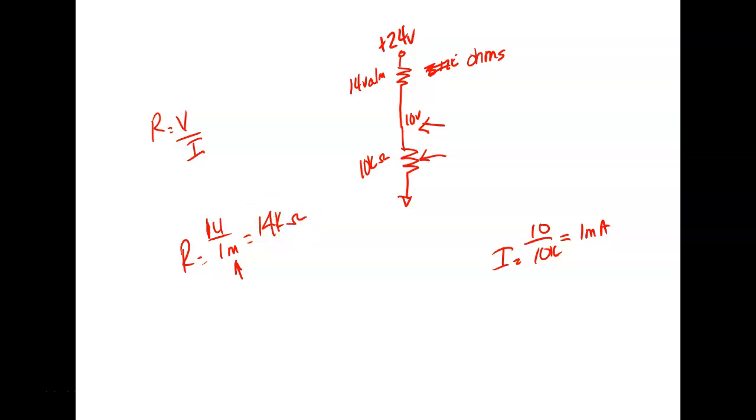So we came in here one time, we had a 24 volt relay that we were going to use. All I had available was 120. I had a 24 volt, 100 ohm relay, and I wanted to hook it up to a 120 volt supply. What did I put in series with it? A resistor. How did I calculate it? 24 volts, 100 ohms, right? Calculate the current, then choose the resistor to run that relay. Of course, we need some more stuff. What else do we need to know about a resistor besides its ohms?